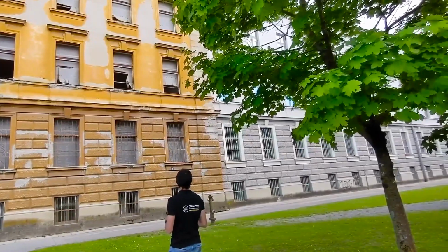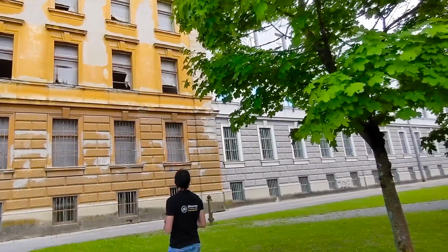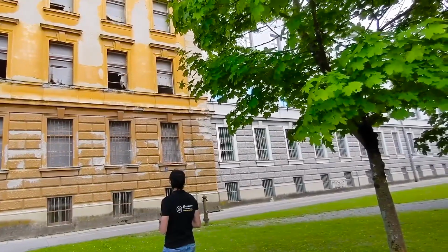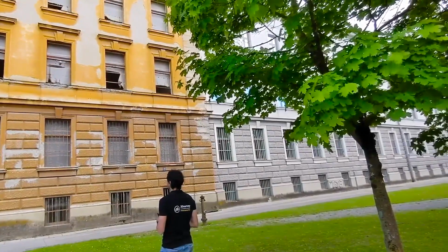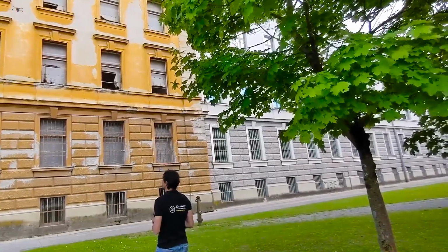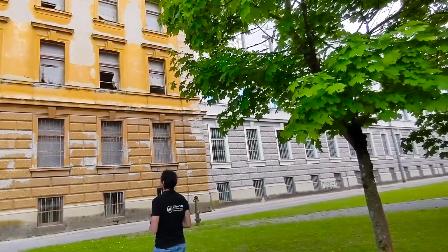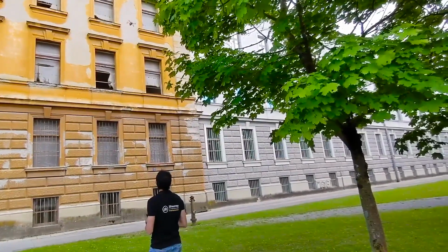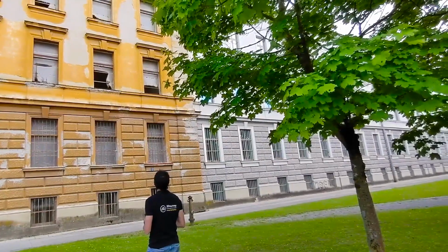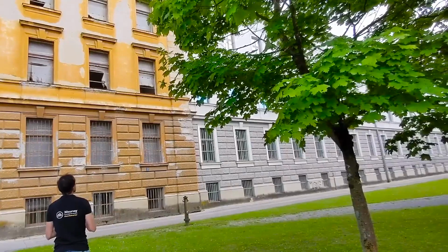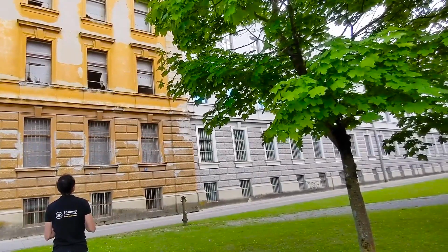As you can see, I'm flying in a horizontal way, stopping every 2 meters and just triggering images, and then raising my flight an additional 2 meters, and flying back and triggering the camera. So it's actually super simple. Just for your feeling, I'm about 5 meters away from the objects because I really like to have images with good quality, with high resolution, because this will deliver me at the end a nice point cloud and a great orthophoto.